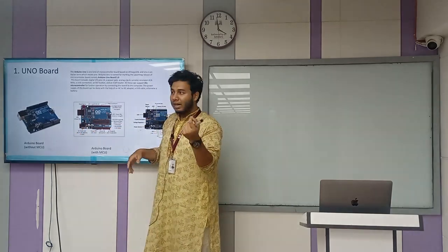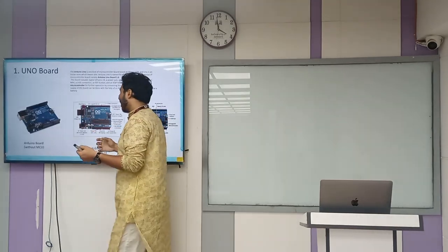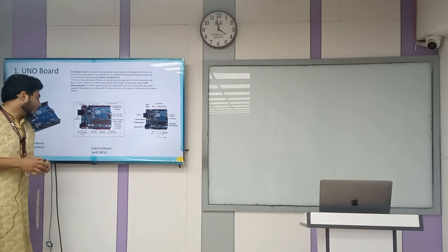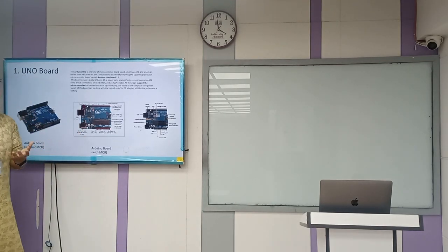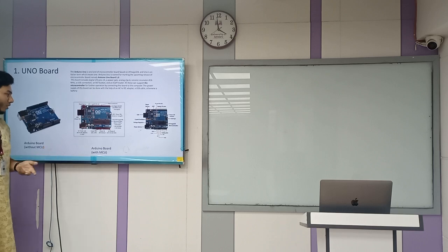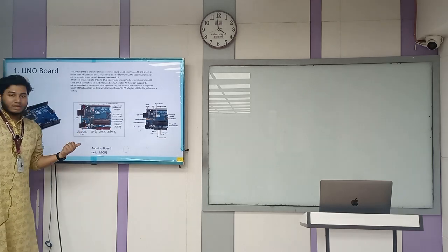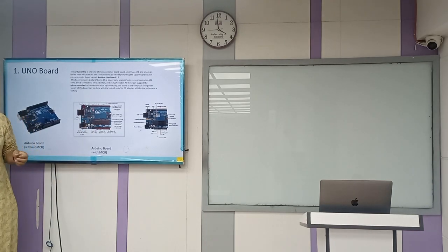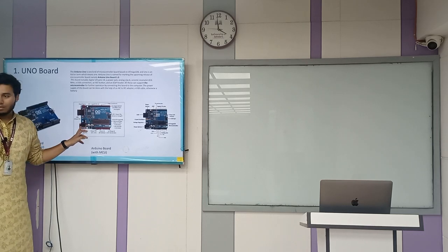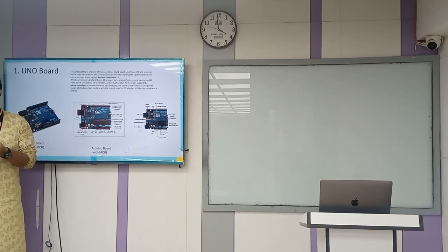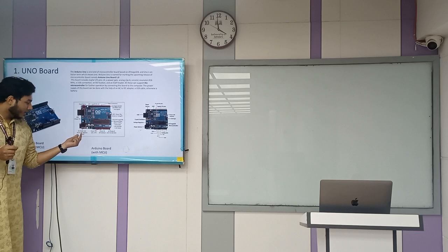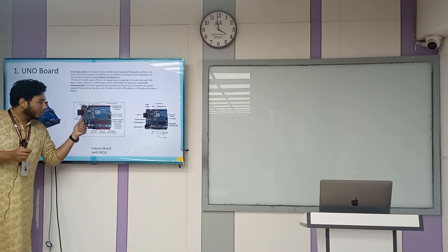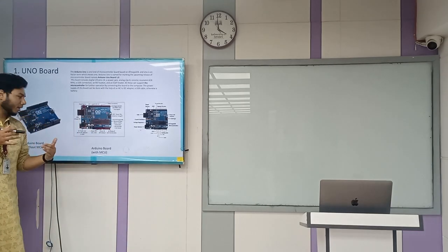And if you want to connect it with an adapter or any kind of charger, then you have AC current, 2 pins or 3 pins, whatever it has. But at the output end, you need a 3 mm jack, because there is a hole over there to make a compact connection with the 3 mm jack, and that power jack will supply this Arduino board from 7 to 12.